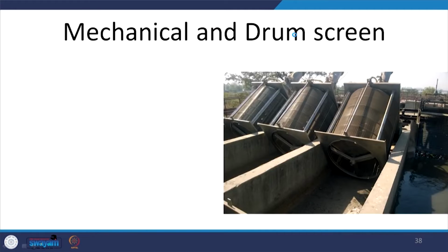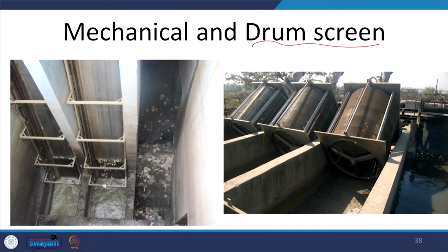So, mechanical, and in mechanical screening we also have drum screens. Again, this is where we are looking at relatively finer particles, depending on the size of the pores in this screen. But again, as I mentioned, in wastewater plants, people typically do not go for that. Depending on the waste or your design, you might want to. Again, the issue is that the maintenance is high, but again, mechanical screens, front end and such, and manual out here, right, front end and manual.